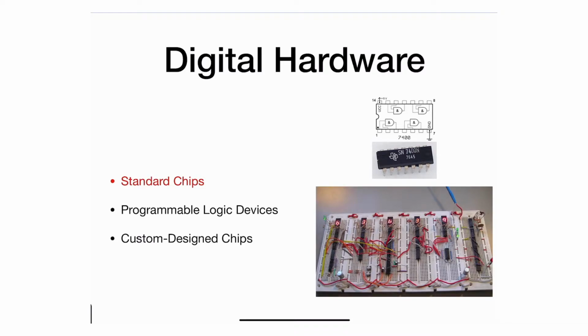Neat is probably not scientific. What I mean by neat is they take a lot of space and they consume a lot of power. So in order for you, for example, to use this NAND gate, you need to power the whole chip. So you're even powering the other gates, maybe ones you don't need, but you're powering the whole chip. So they consume a lot of power. So nowadays there are other options, the programmable logic devices and custom design logic. They're more efficient. They're actually the ones that are used nowadays.